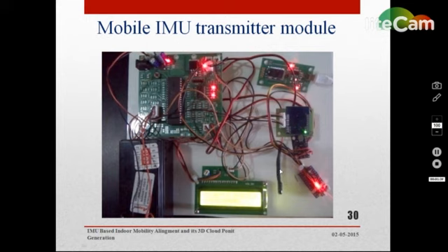This tap sensor gives the step movement for each tap, and it is in a transceiver module which is connected with an FTDI cable to a PC, which is not shown in this figure. This is the overall big microcontroller, and this is the transmitter module, and for each transmission the green LED blinks. This tap sensor can be placed on a foot so that the ideal step movement can be calculated.